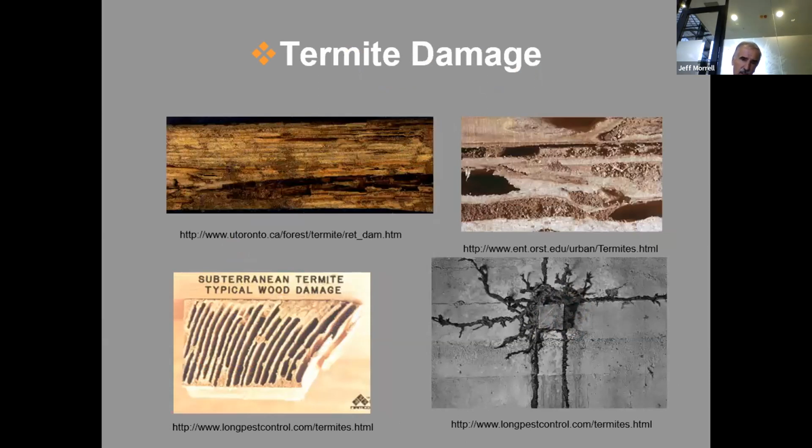Termite damage can vary. For subterranean and dampwood termites, it tends to be very dirty. They don't leave the nest, so they leave their frass, or their droppings, within the nest. They can also make mud tubes, and on the lower right-hand side, you can see where a termite has come in on that piece of timber in the middle. There are tubes going out so the termite can explore for other food sources along that masonry wall. So they can cause a lot of damage very quickly.